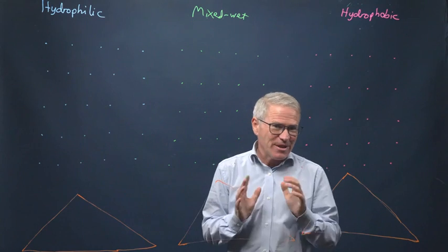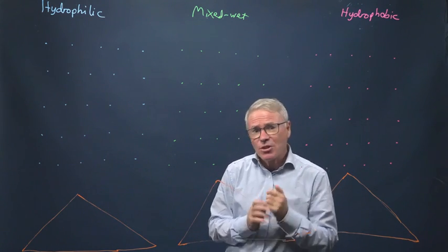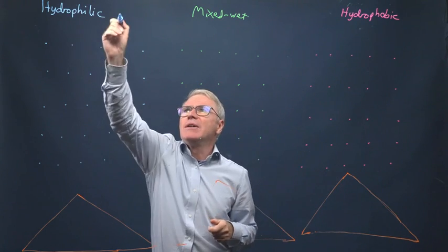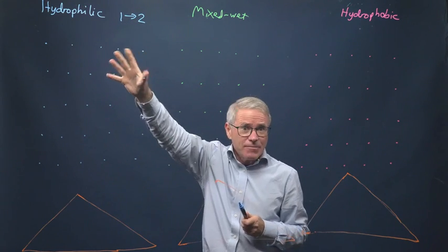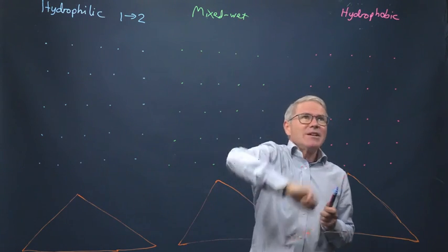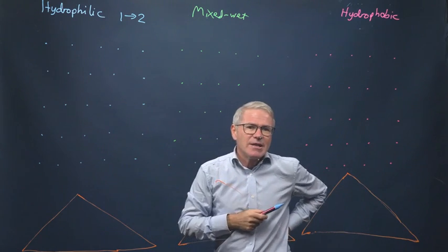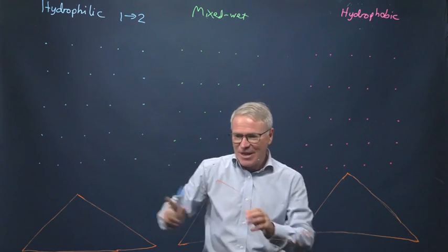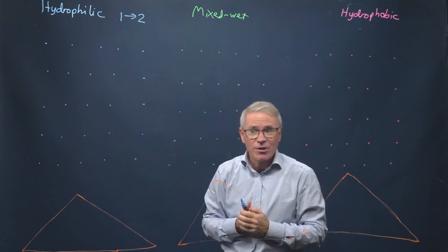We've introduced the relative permeability functions, but to understand those a bit more, what I'm going to do is I'm going to just look schematically at the displacement process. Again, this is going to be phase 1 displacing phase 2 under 3 conditions. One is hydrophilic. So phase 1 is the wetting phase. The water is wetting. The other is mixed wet. And the other is hydrophobic or oil wet. So what these points represent is they represent the pores and the connections between them are the throats, and we're going to annotate those. And then under here is a typical cross-section of a pore or throat to look at the configuration of the fluids.